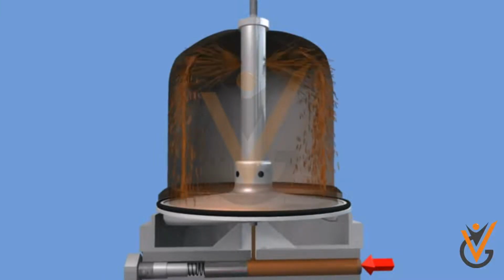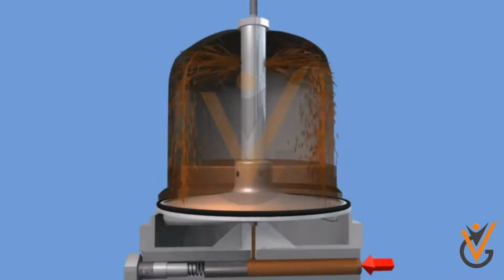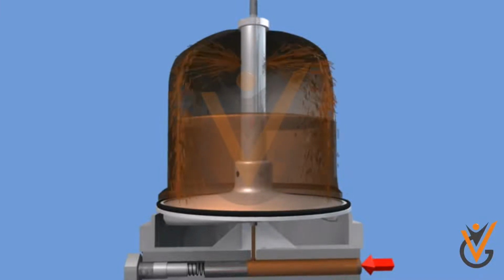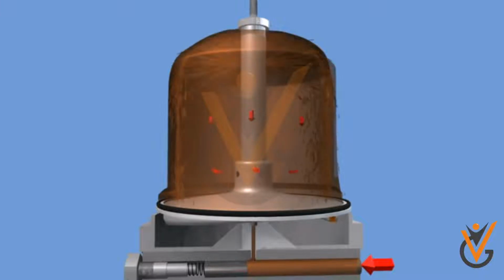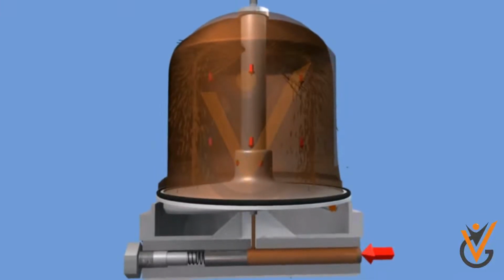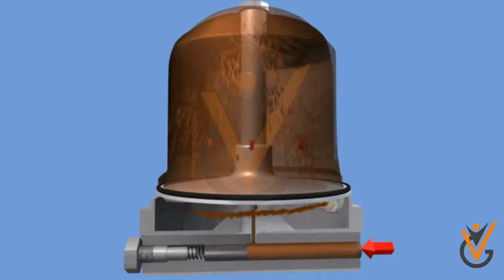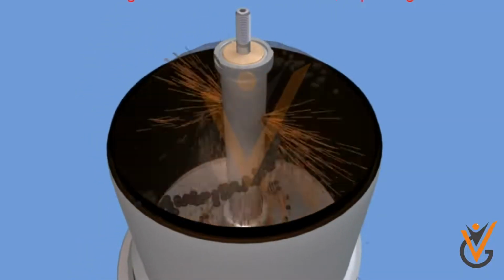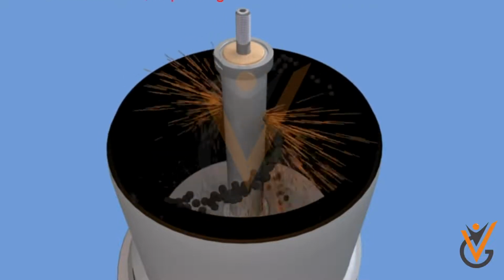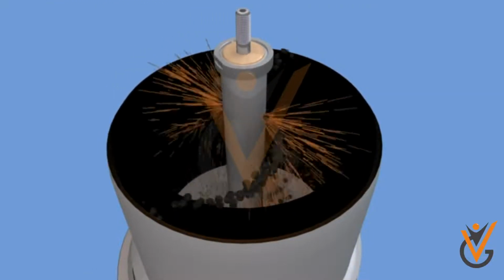These filters have to be taken out and the dense sludge cake has to be removed. Sharp objects should not be used to remove the sludge as it may damage the bowl. A paper layer has to be inserted inside the bowl cover so that the sludge deposits on the paper, as removing the paper is easy and reduces the damage to the bowl body.